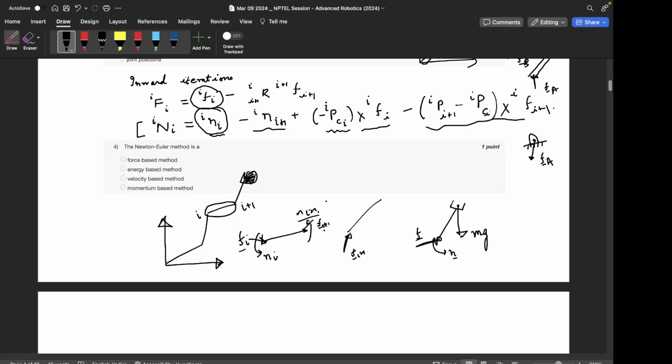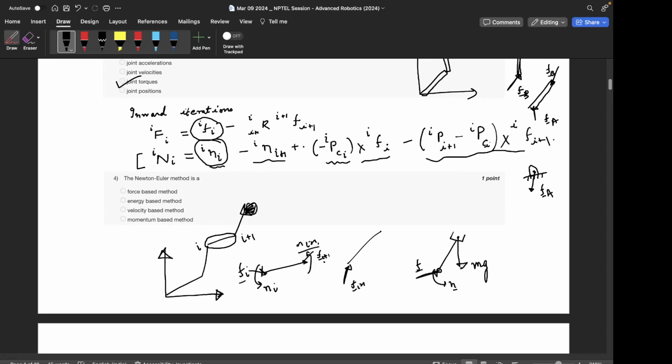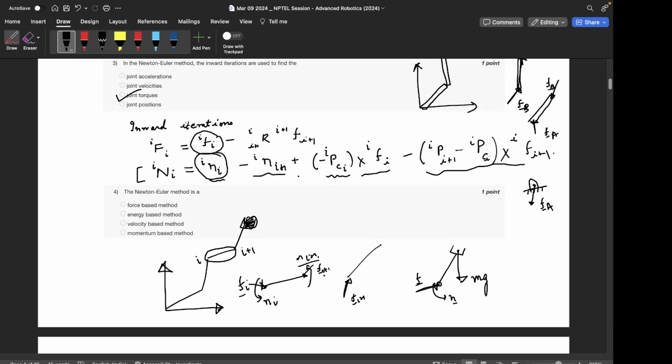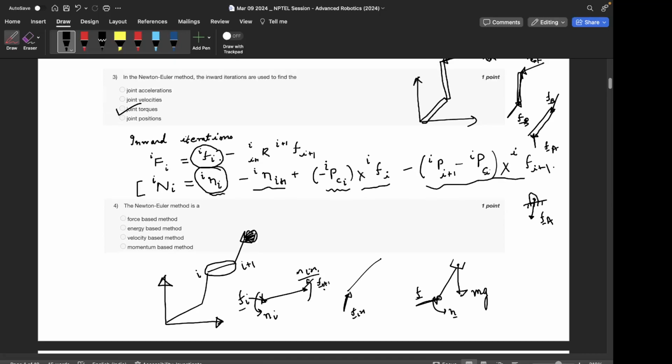At first, when we balance force, some imbalance in moment is created. So for that we solve in the next step, isn't it? No, it's not like that. To solve for the force balance, we don't need any extra information, and for solving the moment balance, we do need the force information, right? So we can't solve the second equation before the first, because the second equation needs these f i and f i plus 1. So first we solve the force balance. Force balance just needs these two forces.